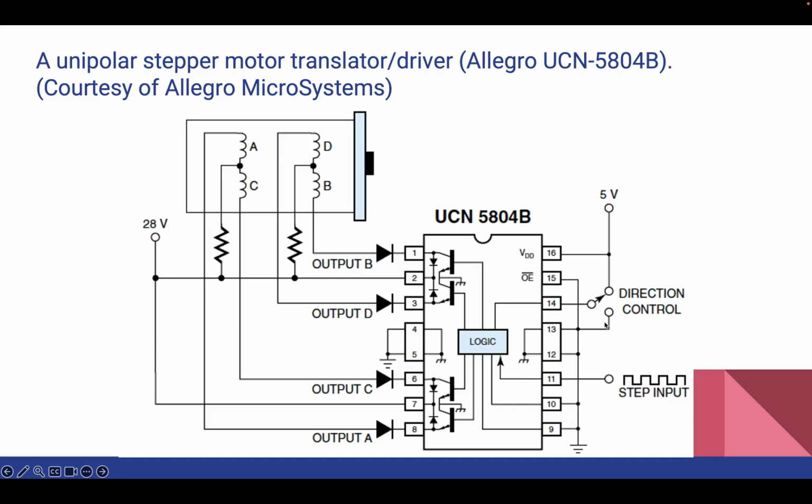And the output transistors, as you can see, these are the output transistors. They are basically a common emitter arrangement, also known as open collector, and this configuration simplifies the circuit design and also offers flexibility in connecting external components.